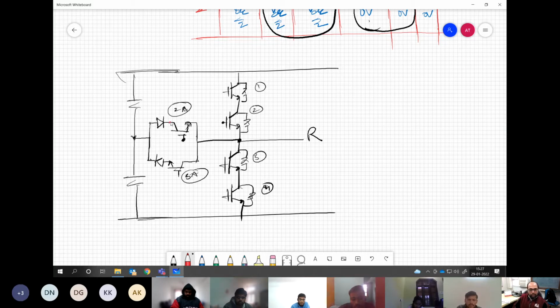So can I not connect these 2 points without any trouble? Can I connect? Yes, sir. Can connect, right? Potential is already the same at one terminal, and the other terminal also has the same potential. When we say the drop across the device is equal and one terminal has the same voltage, that means the voltage at the other terminal is also the same. So we can connect the points which are at the same potential with simply a wire without any problem.